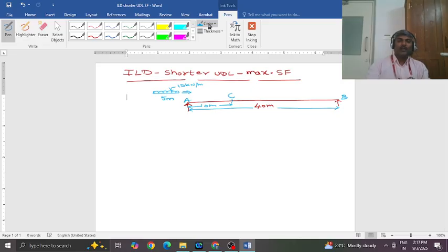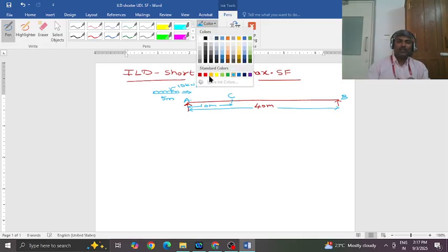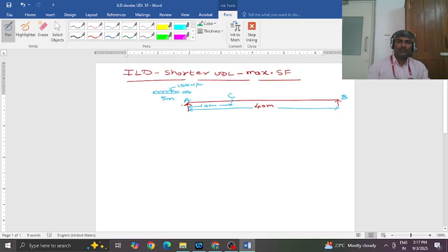Okay, right. So we are interested in the shear force. So we need to plot ILD for shear force at a section. Okay, let us plot ILD for shear force at a section. So we draw a reference line, then drop this section onto the reference line.